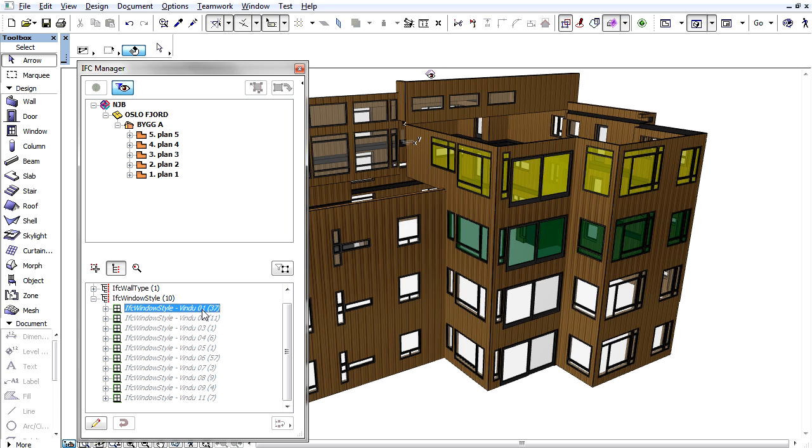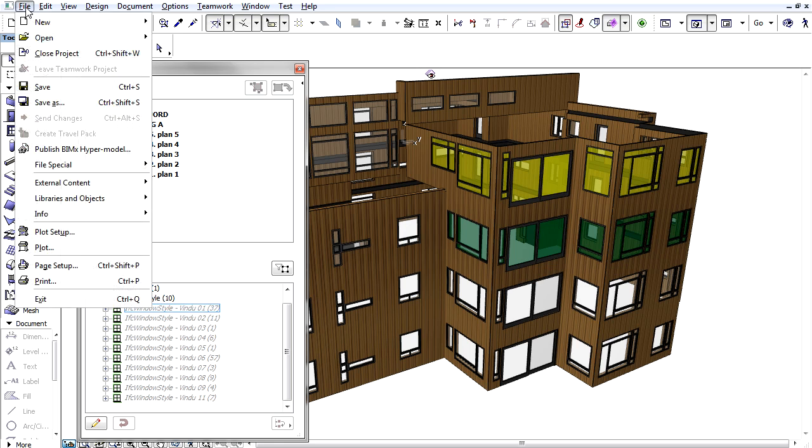You might have placed a single window element several times, using different sizes and styles each time, but you can't see the difference in these type categories. But suppose you're using an IFC standard that requires you to differentiate your windows further. The solution is to change the naming rule so that it includes more parameters besides the library part name. This is where data mapping is very handy.